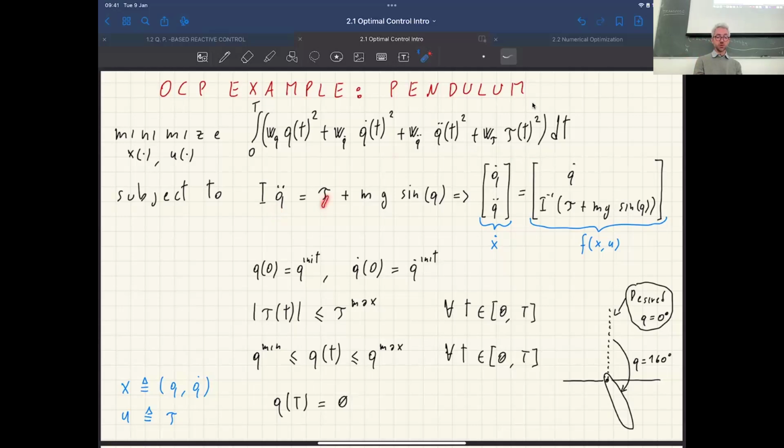As you make the torque higher, you're also making the acceleration higher. So in general, I would either minimize the torques or the accelerations. Minimizing both feels a bit redundant, but could be done. It's not a problem. And that's going to result in having torques that are a bit smaller and also smoother.